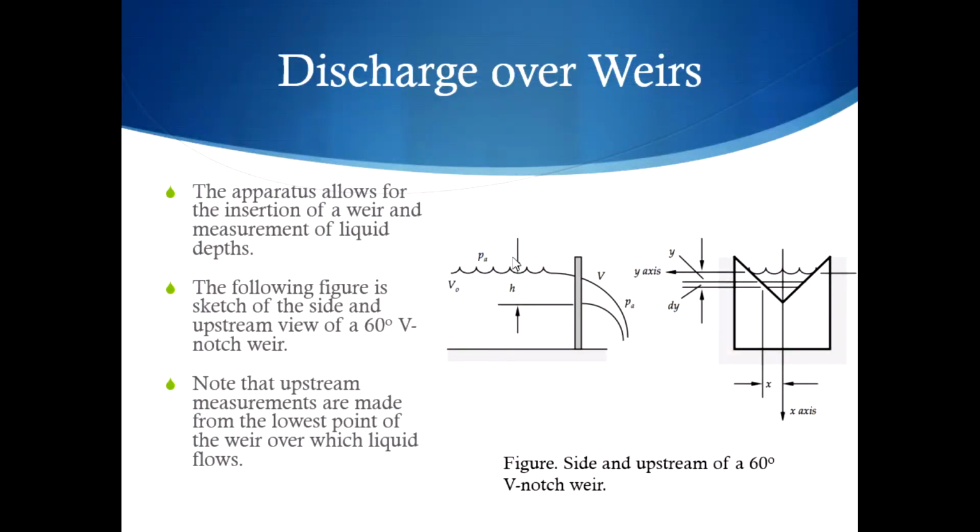So our base measurement we need to take in the experiment is that we need to know this head, which will work as a base. So for example, we have our weir, and we need to calculate the head of the base of the weir to have a base H. So we will calculate this H, and then we will turn on our pump, and then we will generate flow. When we generate flow, we will create a different H, so then we will calculate this H. And the difference between these two measurements will be our delta H.